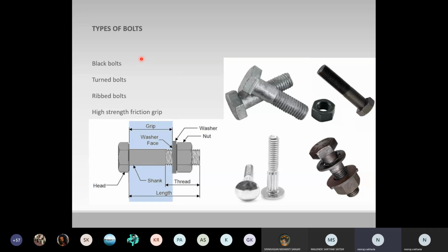These bolts are made of mild steel, and they are generally used for light structures under static load, such as small trusses or purlins, etc. We don't make them experience heavy loading or main structural elements to be connected with these bolts.